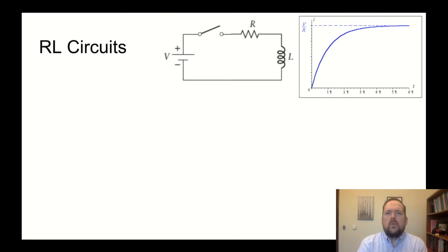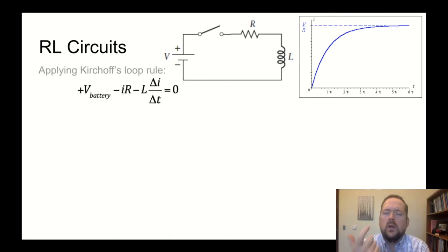So what happens when you put a solenoid in a circuit? Well, if you did the lab here, you saw this effect. So here is a diagram of a solenoid wired with a resistor into a DC circuit. And when you close the switch, current starts flowing, but not immediately, because when current starts flowing through that inductor, it induces a back EMF, which fights against the increase in current for a brief period of time before the system settles down into a steady state current that's flowing there.